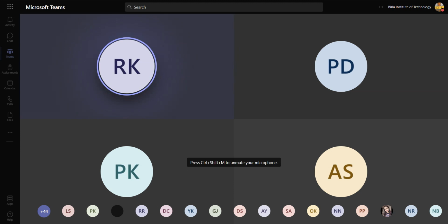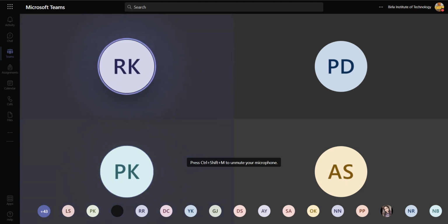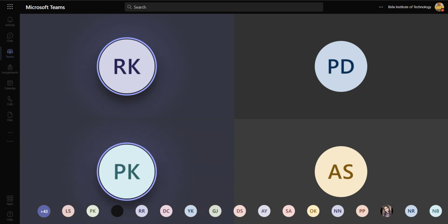Now connect it. Go back to circuitry. Now do the connection. One ground you need to select, no? So you come to basic, sources, ground.